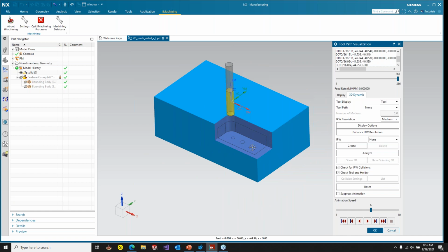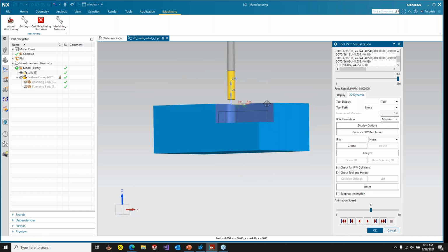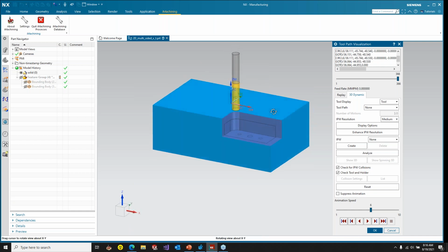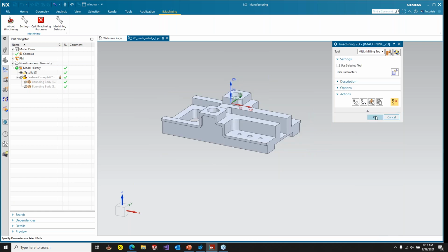So we machined this pocket. As I said, it extended it out. The feature recognition automatically extended it out, automatically determined the upper level based on the updated stock, and gave us a perfect toolpath without having to do any geometry picking. We didn't have to set any levels. So this is a huge upgrade for our customers in NX.